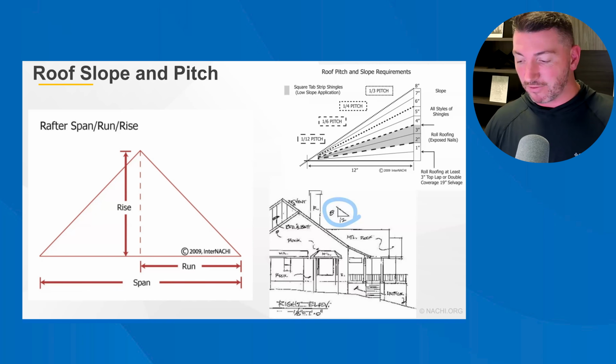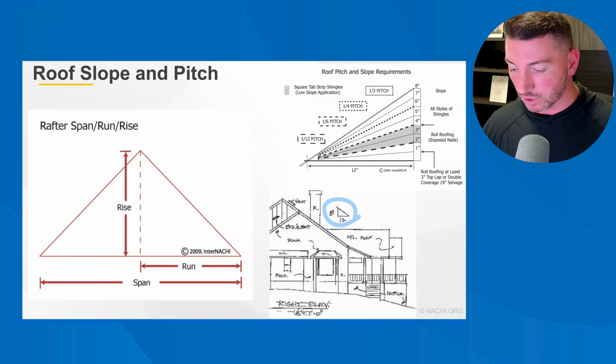A roof that rises 8 feet over a 24-foot span is said to have a 1:3 pitch. If the rise was 4 feet over a 24-foot span, then the roof pitch is said to be 1:6. The pitch can be expressed numerically as a fraction. The pitch fraction is different from the slope. It represents a certain amount of vertical rise over the entire span. For example, given a roof with a rise of 4 feet and a full span of 24 feet, the pitch is 1:6, which can be expressed as the fraction 1/6. A 12 to 24 pitch is expressed as 1:2, or 1/2.